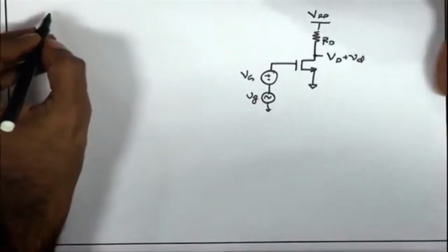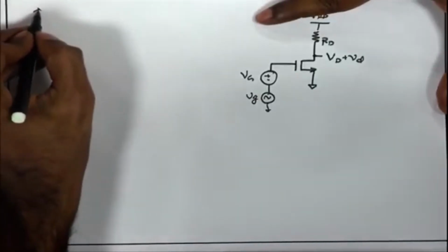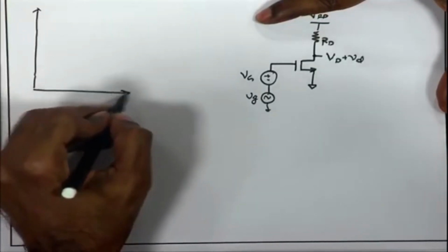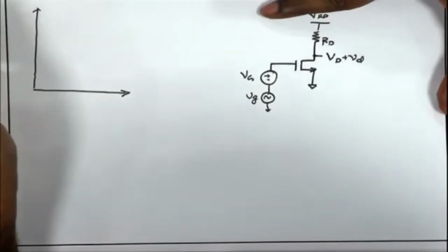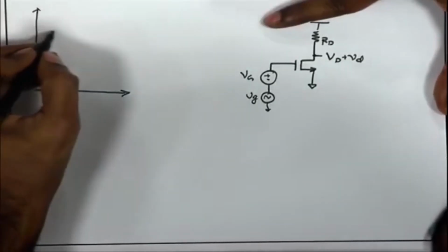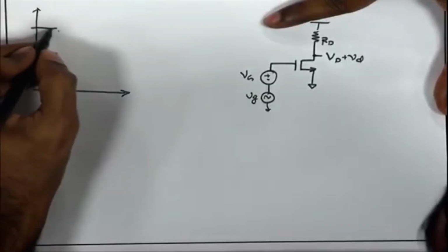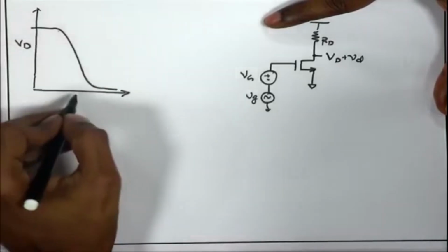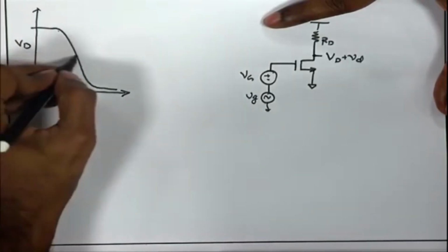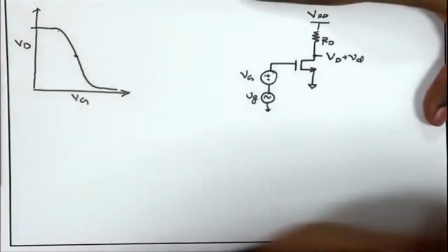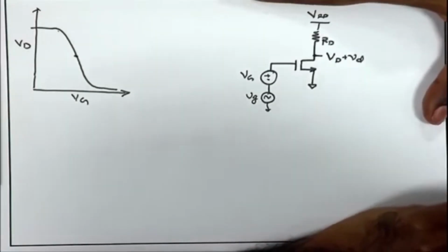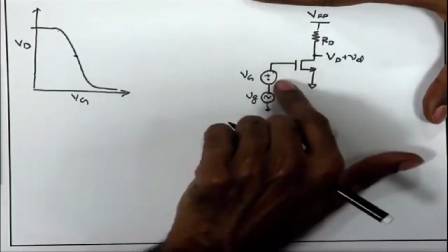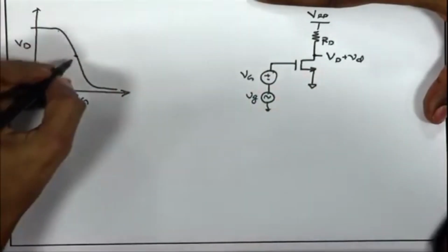Now, if we talk about the best possible biasing point, we need to look at certain considerations. One is definitely the gain, and we see that in the central region we are going to get possibly the largest gain. Another important consideration happens to be the signal swing that is available to us. So, if I look at the DC voltage at the gate, suppose capital Vg,